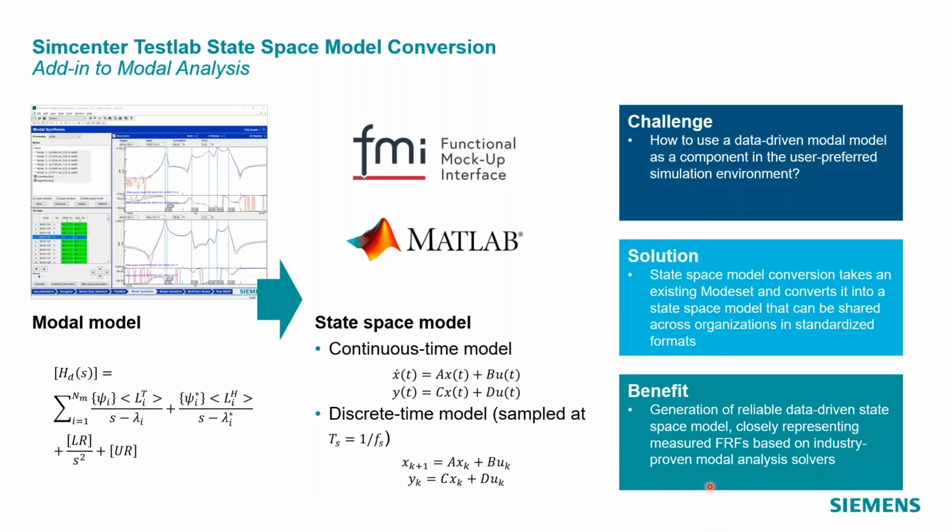The benefit of this solution is that we will generate reliable models that closely represent our measurement data, thanks to the stabilization diagram interpretation, MLMM. So we have industry-proven solvers. In the software, you can also check the quality of your state space model before exporting it and passing it on to a colleague, perhaps. So you're quite sure about the quality of your model.